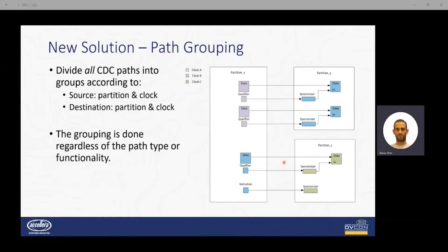And in the second group, we even have a single bit synchronizer, which is an actual real false path. We don't need to make sure it meets any timing skew requirements, yet we group it together with a bus synchronization scheme that does need to meet the timing skew requirements.